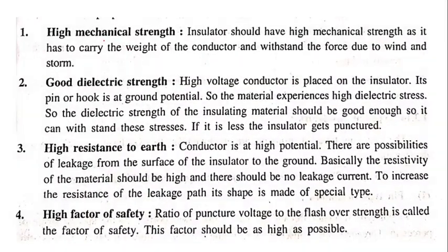So the first property is high mechanical strength. An insulator should have high mechanical strength as it has to carry the weight of the conductor and withstand the force due to wind, storm or ice. So it should have high mechanical strength.